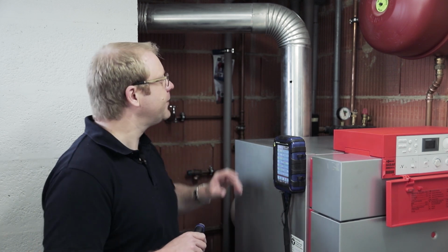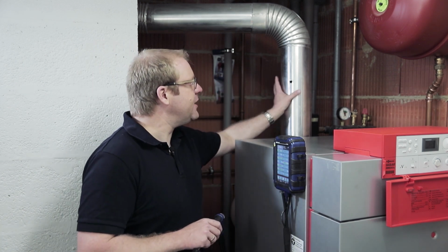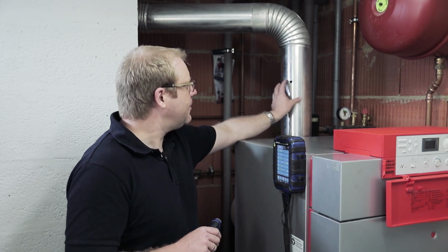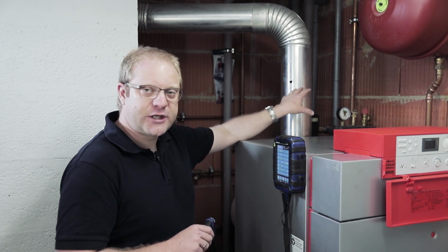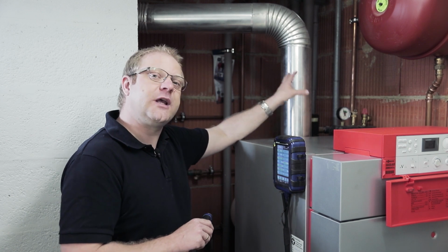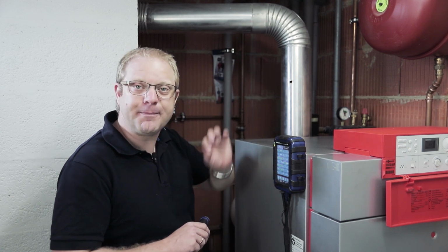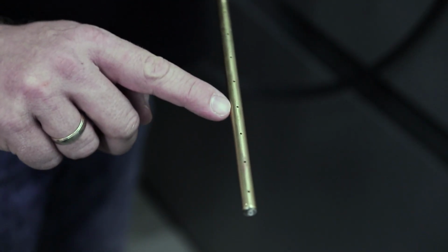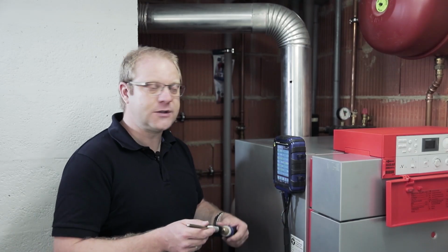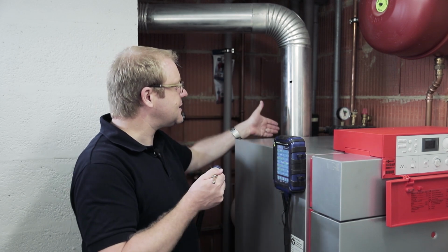When measuring, it is important to use a special multi-hole probe for the following reason. In the flue gas flow, there are often places in the connecting pieces of these appliances where there is a lot of carbon monoxide, whereas there are also places where there is little carbon monoxide. It is therefore necessary to determine the entire cross-section, and this is only possible with a special multi-hole probe. The holes must of course be in the opposite direction to the flue gas flow.